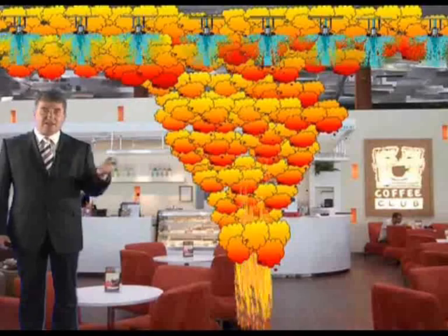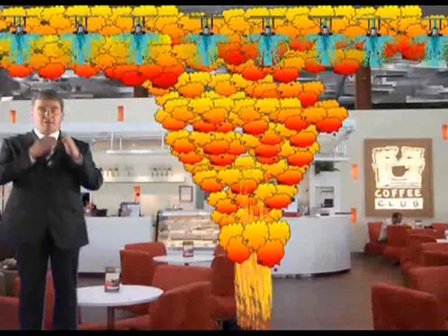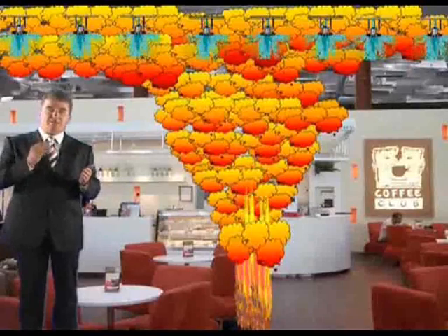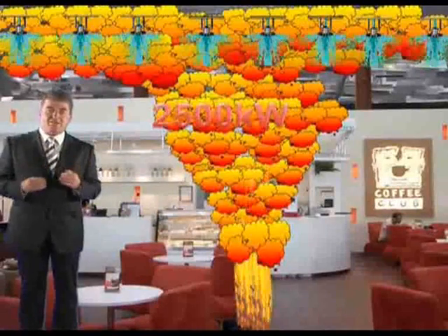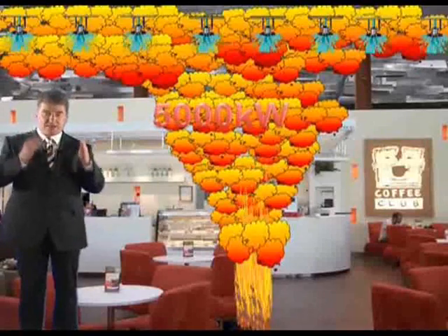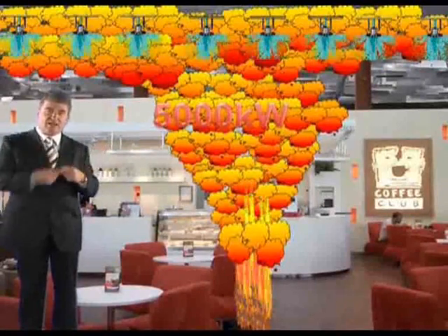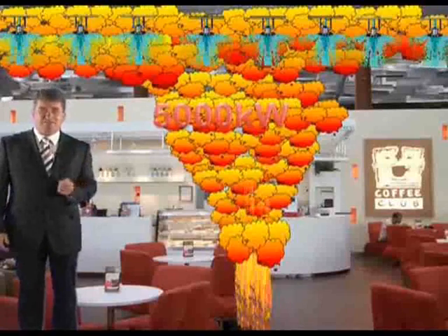It's important to remember that sprinklers in shops are an essential part of the smoke ventilation system design in order to prevent the fire growing beyond what we call the design fire size. For example, in shopping malls, you should put fast response sprinklers in. If you put fast response sprinklers in, maximum fire size should be 2.5 megawatts. With normal sprinklers, you've got a 5 megawatt fire, but it limits the fire size so that you can work out the smoke extraction rate, and you can make sure the system can deal with it.